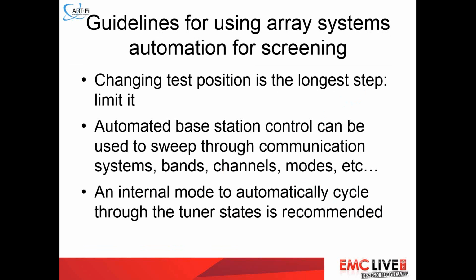When using array systems, maybe some guidelines are good, like when you want to use them for screening. Especially with the modern array systems, there are some nice automation features, like for example controlling the base station remotely to sweep through all the communication systems, bands, channels, modes pretty efficiently. In such a case, changing test position is usually the longest step. So it may be better to just fix one position and then go through all the modes, bands, channels first, instead of changing the position every now and then.